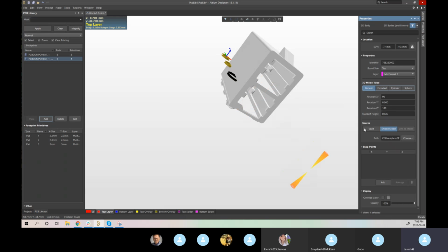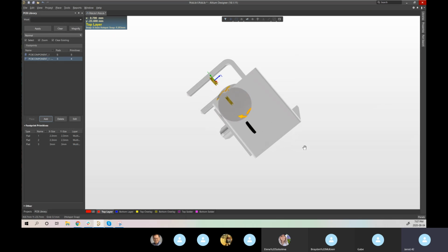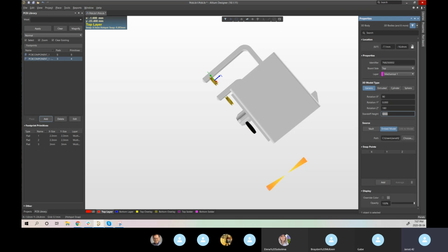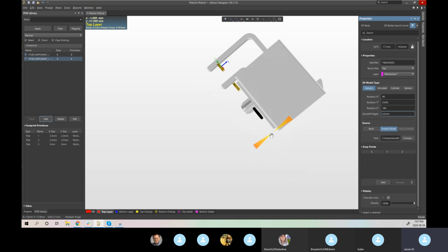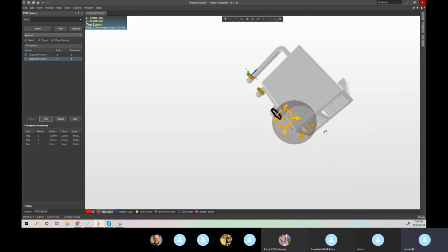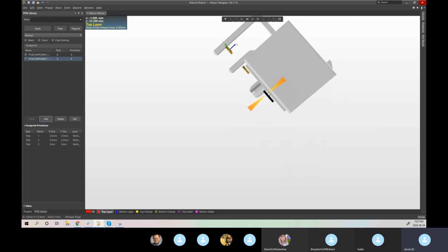You do just have to play with the XYZ. It's typically by perfect 90-degree rotations to get it to the proper orientation that you're designing. And then we can see that it's sitting in what would be the middle of a PCB, so we have to change the offset to something. It doesn't really matter, so I made it 4.5, but we can see that would actually leave it floating a little bit. You don't have to make it perfect.